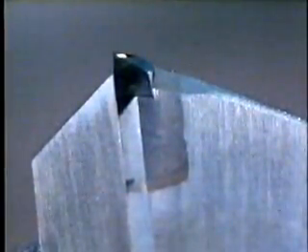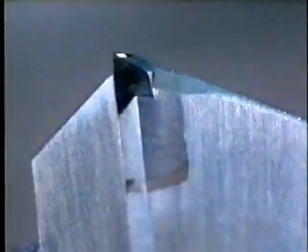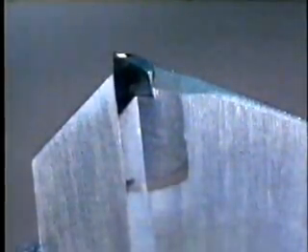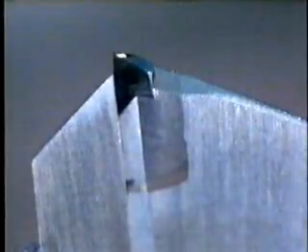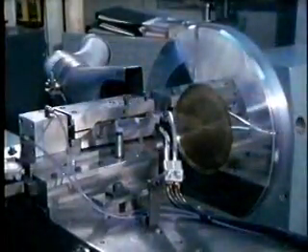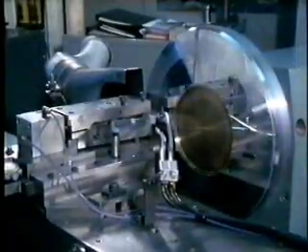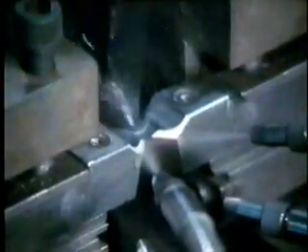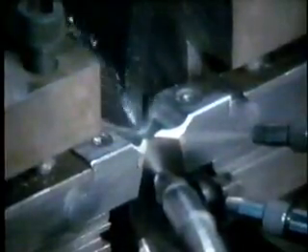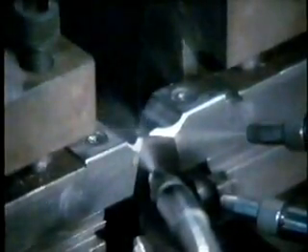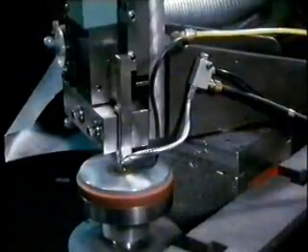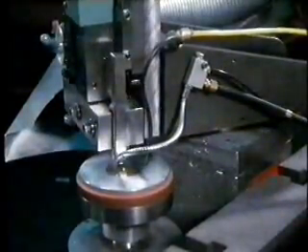When the appropriate stones have been selected, they're carefully mounted, making sure that they're properly aligned. Diamond tools are best used on vibration-free equipment, such as this lathe, which is specially designed to put the finishing cuts on aluminium computer memory disks. To give the discs the best surface finish possible, cutting speeds are very high. In this case, they are 4,000 revs per minute.